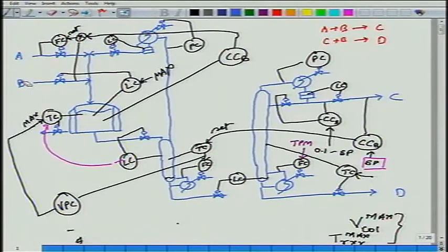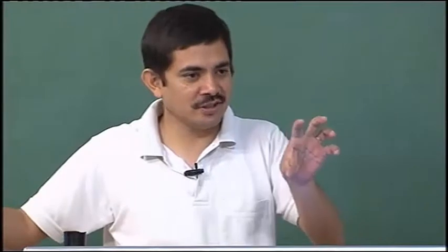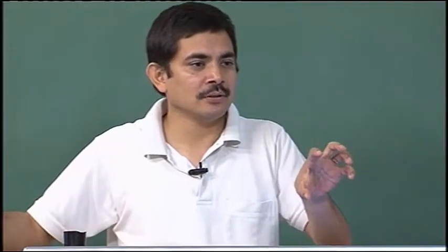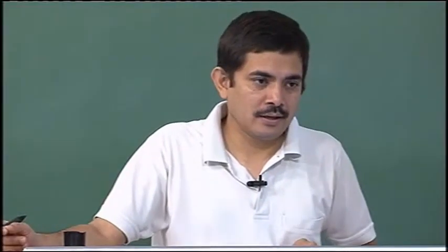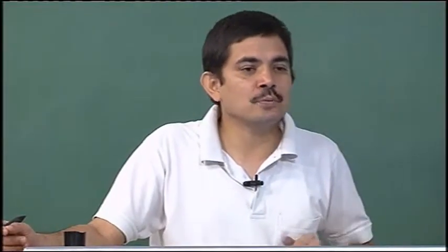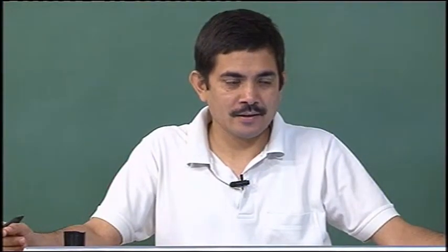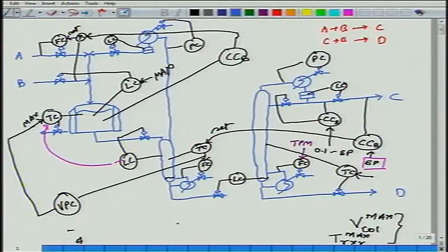When you sum it over the whole year, the extra B that you are consuming because the selectivity is 0.2% lower can amount to a lot of extra raw material consumed for the same amount of C produced, right, and that can run into crores of rupees per year, crores of money spent on extra raw material. Does that make sense or no?